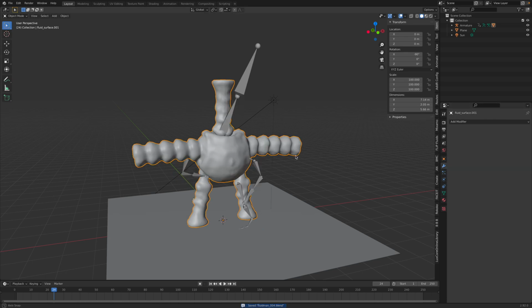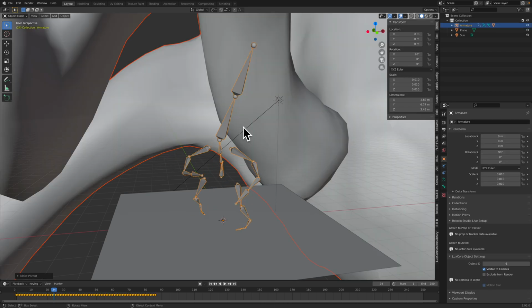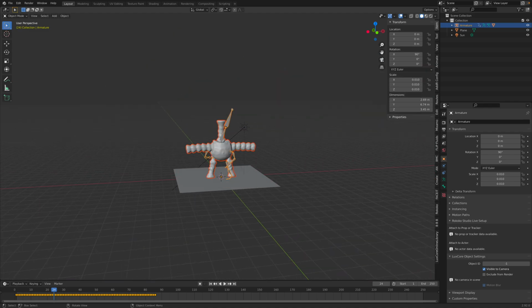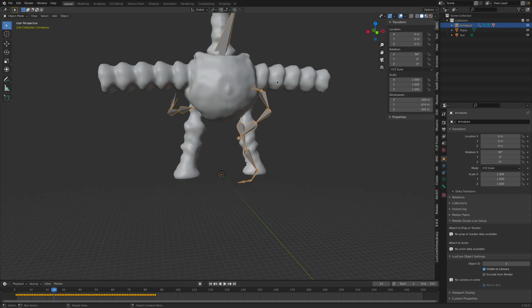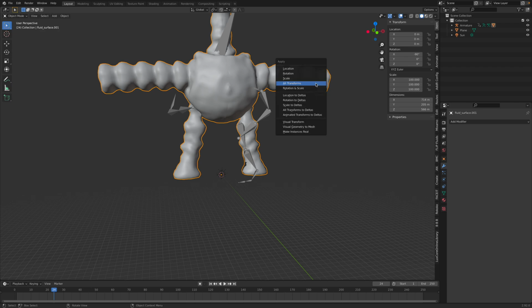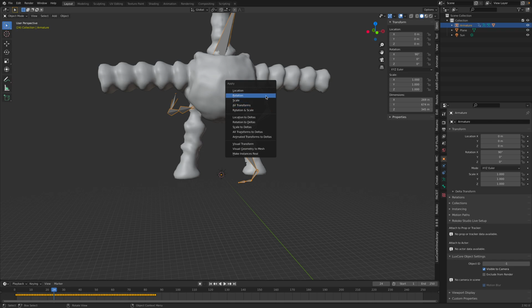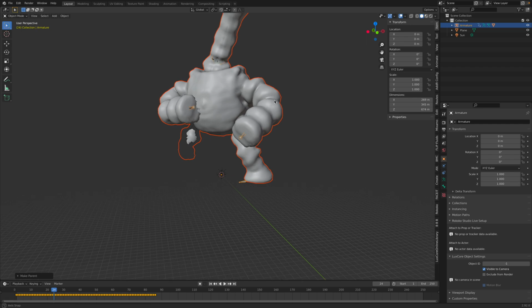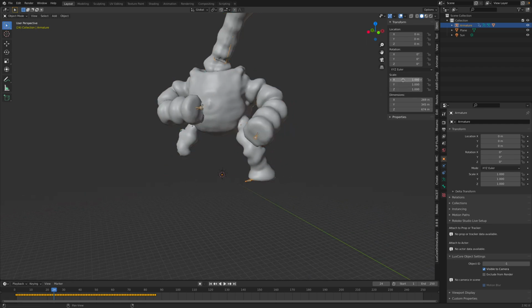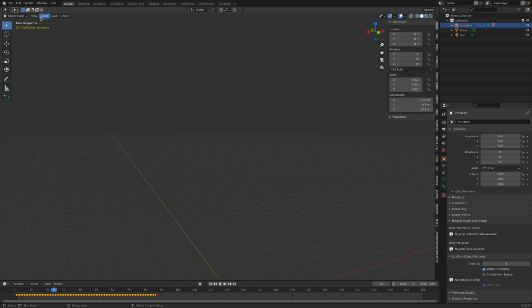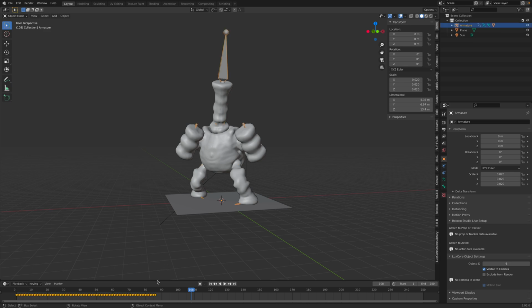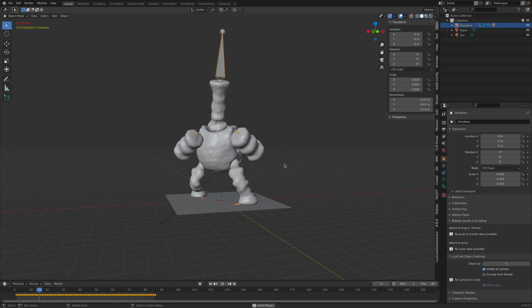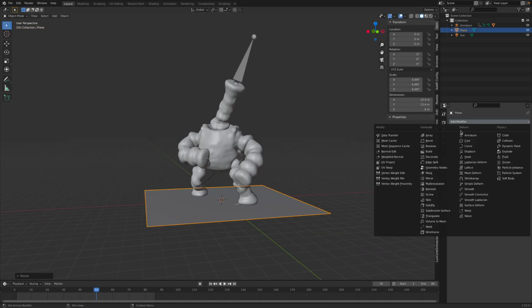if I get rid of this skinning and just reparent it with automatic weights, Blender can do a better job. But you need to be careful with the scaling. This always happens with Mixamo. You have this 90 degrees and scaling. Apply. Reparent. You see the skinning is much better. Yeah, you just need to be careful there. So we have our fluid character doing a taunt. Solidify.